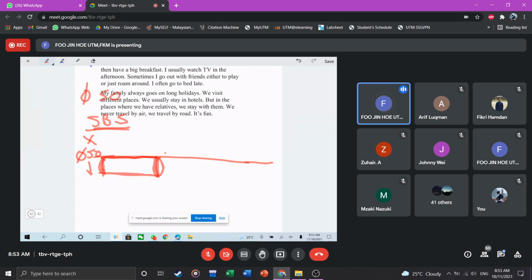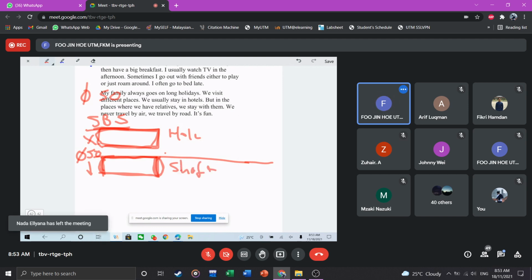So whenever, let's say, you produce a hole that is bigger, like it shows you on top, this is the hole, this is the shaft. If the size is always on top of this shaft, it means there will be no problem inserting the shaft into the hole. You always get a loose assembly. The most troublesome one is always in the middle section.